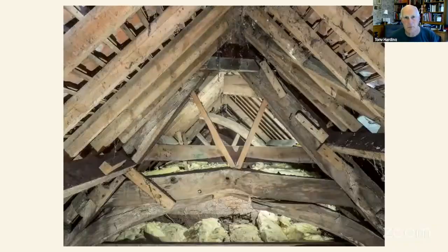If you want to see the upper portion of trusses, generally, that nice roof we looked at is the exception rather than the rule. More often than not, you've got to clamber your way up through a little ceiling hatch, which may be no bigger than a sheet of A3 paper. And when you get up there, you find yourself looking at something like this. Same stuff as there. We've got rafters and collars and arch braces, but it's in amongst a clutter of other stuff.